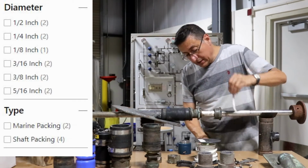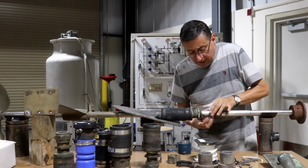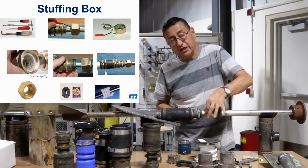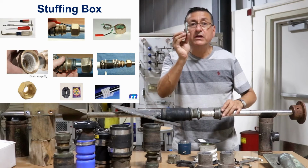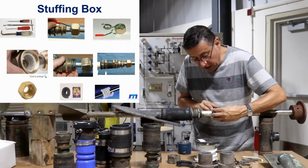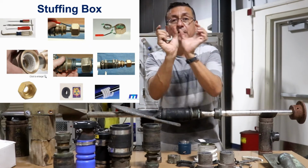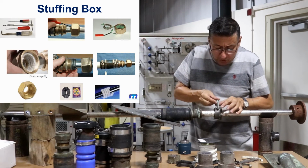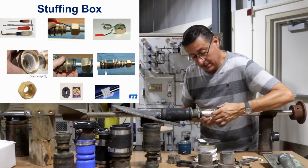You need to cut the material exactly with a razor blade according to the diameter of the shaft. Inside you find three of those rings, located exactly like piston rings, separated 120 degrees to avoid leaks. You have 1, 2, and 3, and they are introduced inside.